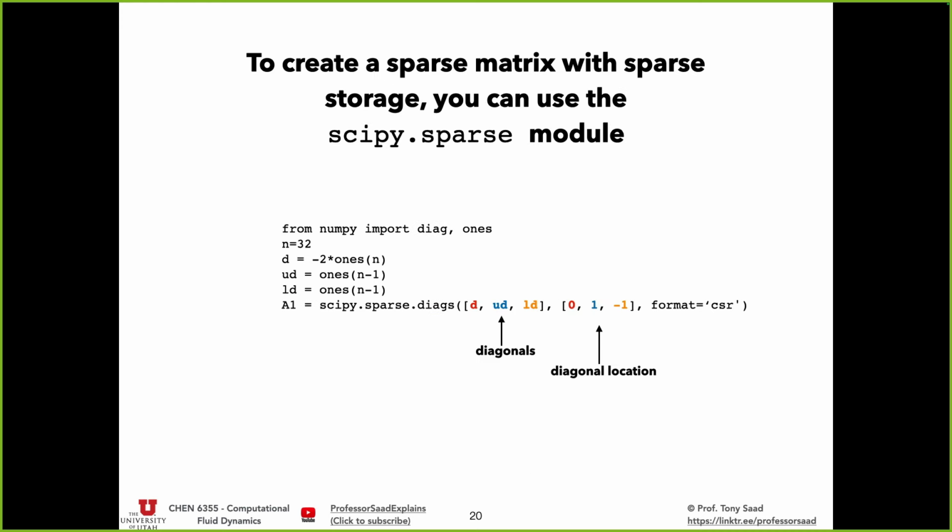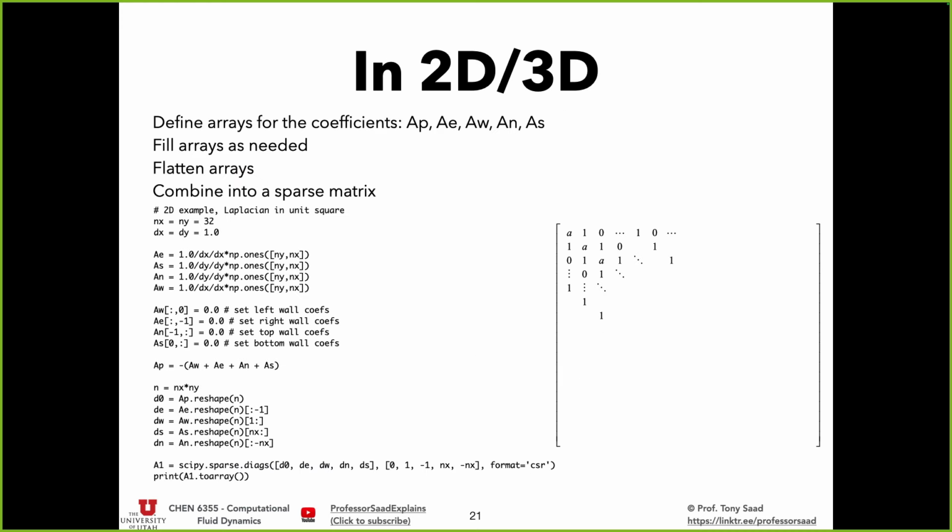Okay, I'm going to just spit out the code for you, because it will take me probably a lecture to explain how this is derived. But what I will do is the same procedure. This is very relevant to us, so you will use this code from here onwards. But here's how it's done. We represent at each grid point, in the finite volume sense or the finite difference, an east, west, north, and south coefficient and a p coefficient, right? So I'm going to represent each one of those coefficients as a full array that is consistent with the grid.